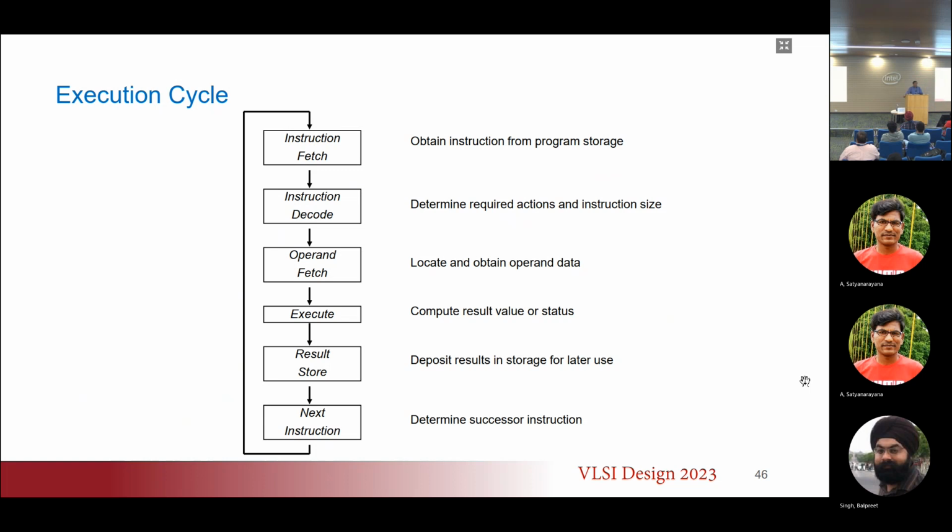Think about it this way: suppose I want to do my convolution operation, and for every convolution operation inside of the loop that you saw, I would like to fetch an instruction that says multiply these two operands. Then for that instruction, I need to fetch two operands, and then I need to fetch an instruction that says add the result back, and then I need to fetch whatever was the previous result.